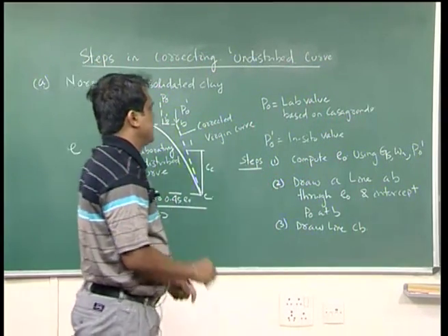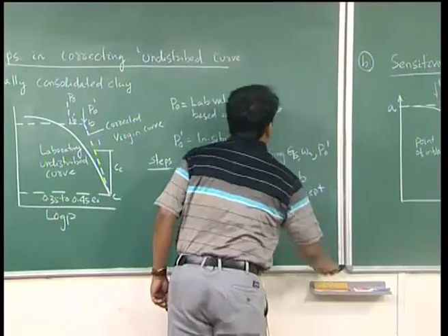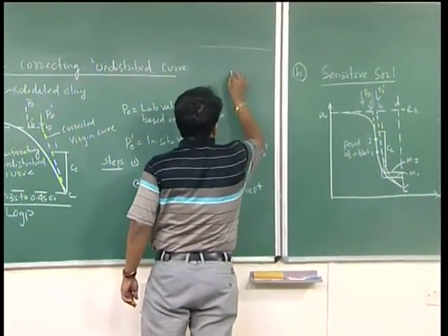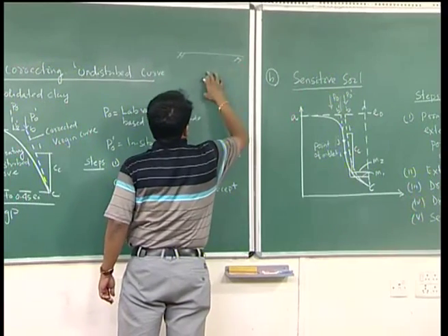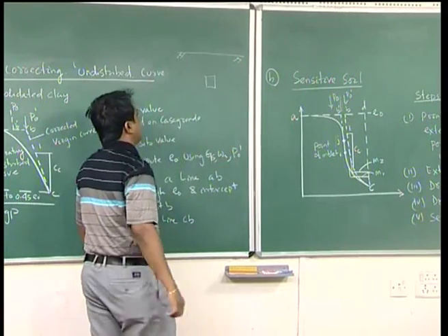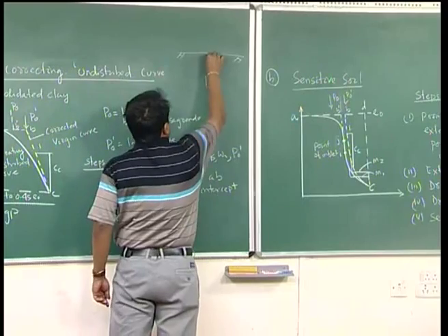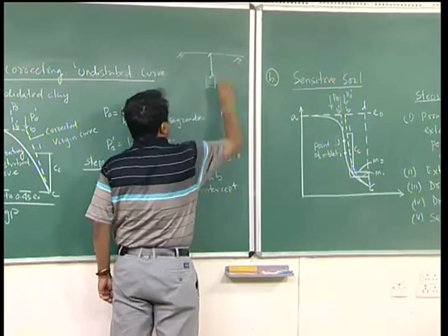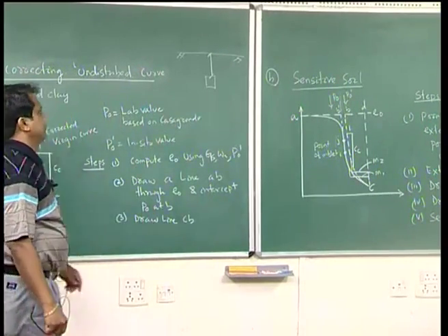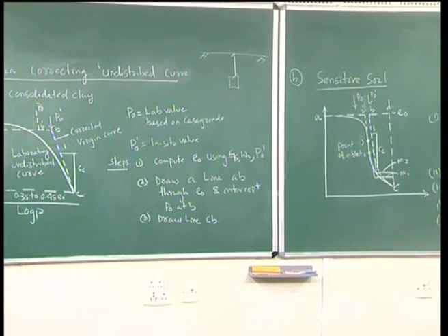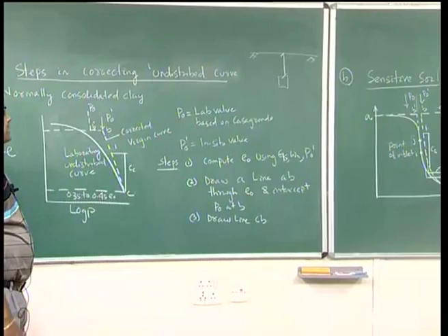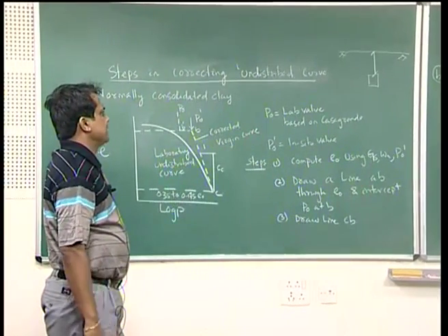As I said earlier, the moment I take the soil out from the field to the lab, the major part of this overburden pressure has gone, and sometimes the confining pressure is also lost, sometimes it is there.